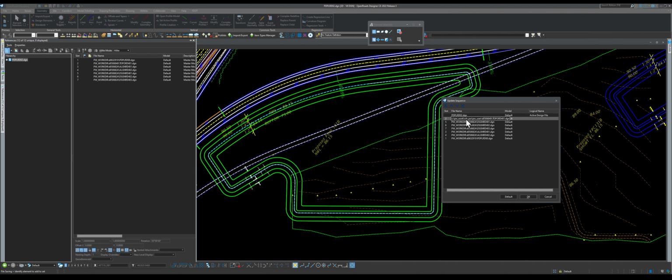The last thing is, you see this thing here? This is actually the same file itself. Meaning, if I also draw stuff here, should I make them in the back or in the front? Of course I want them in the front. So after you set the order that you want, as you can see here, I want my pawn 2D on the top, and then secondary is the alignments, and then the design and the topo. Let's go to this one and push it to the top. Back again. And this is a good order. So now let's click OK.